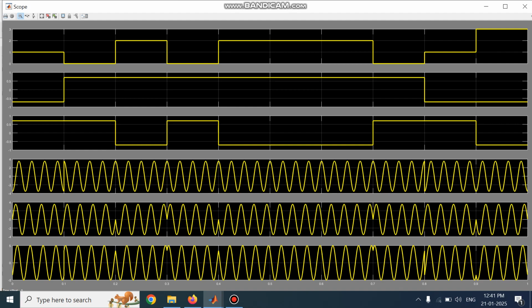The corresponding phase is 45 degree or pi by 4 with respect to cos. So this is pi by 4. Similarly, the next integer is 0. It is represented as 1, 1 in gray code. The corresponding phase is 315 degree. Next integer is 2. It is represented as 1, 0. Phase is 45 degree.